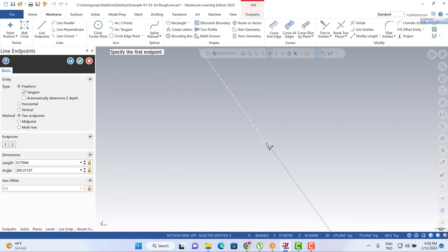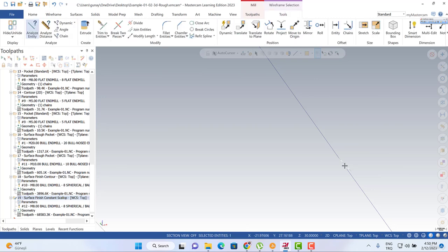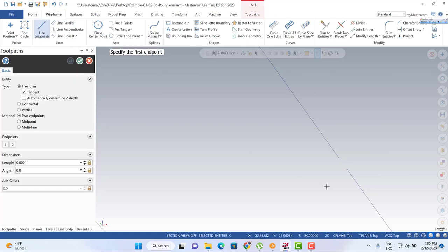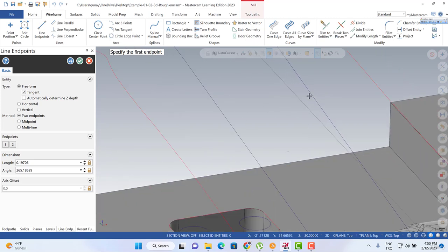As you can see here, for example, we can create a scallop toolpath by using the 3mm diameter for all my faces, but that can also be time consuming, because if you use the 3mm diameter, we need to use less step over.